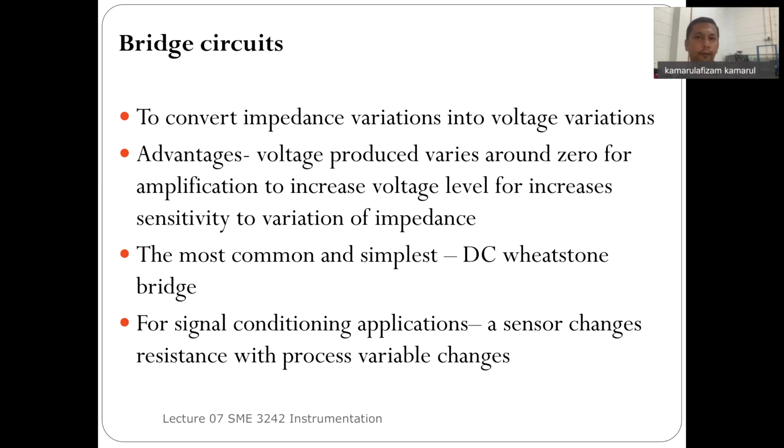All you are getting from the sensors is changes of R. So R, for example, changes from 10 ohms to 20 ohms, and many sensors basically produce this kind of parameter, changes of R. So sensors change impedance to denote the changes in the environmental parameters that they are measuring.